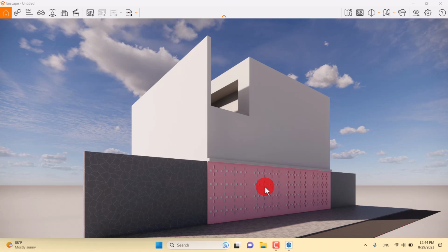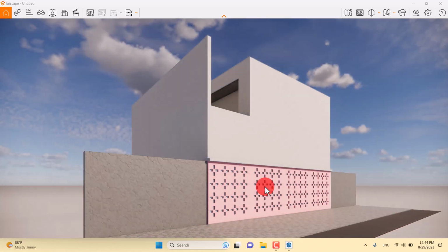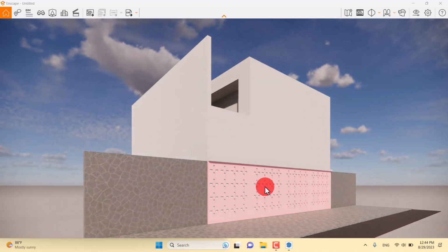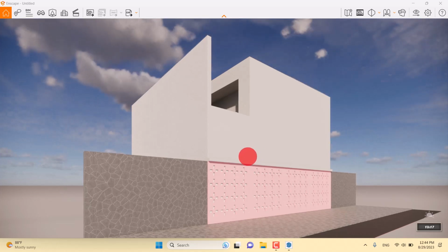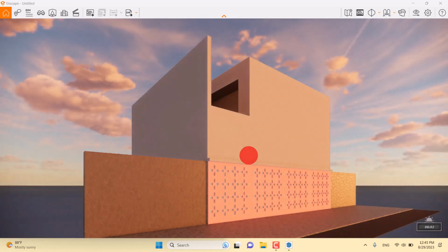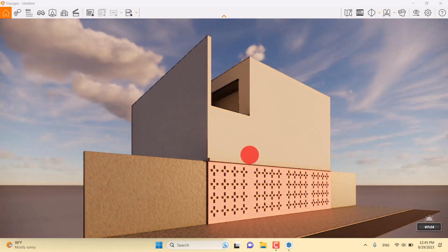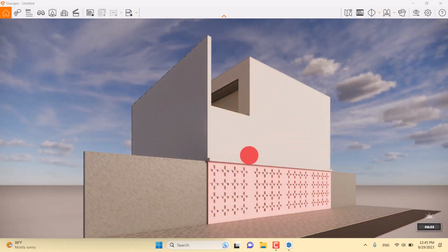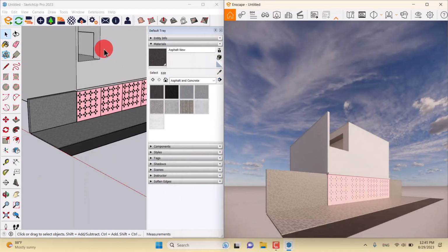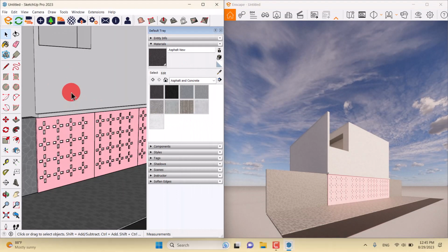First of all, for the realistic rendering, I must check the sun position. I hold Ctrl and U or I for creating this sun direction very simple and easy. And I can hold Shift and right click cursor for making the time of the day very simple. I think some number about 9 a.m. can be really good, so I prefer to use these type of numbers right now. And now I'm gonna start my job with materializing.